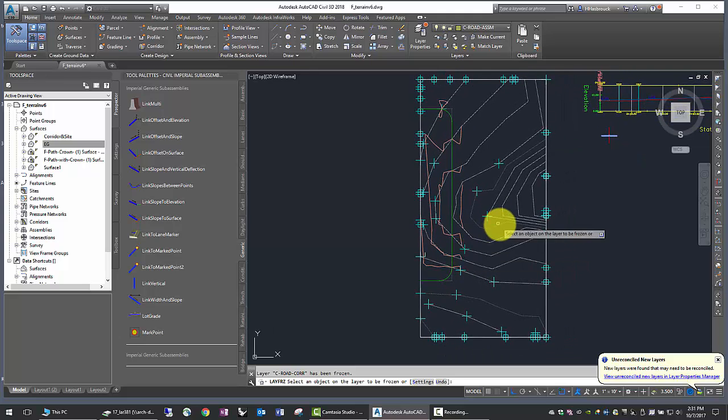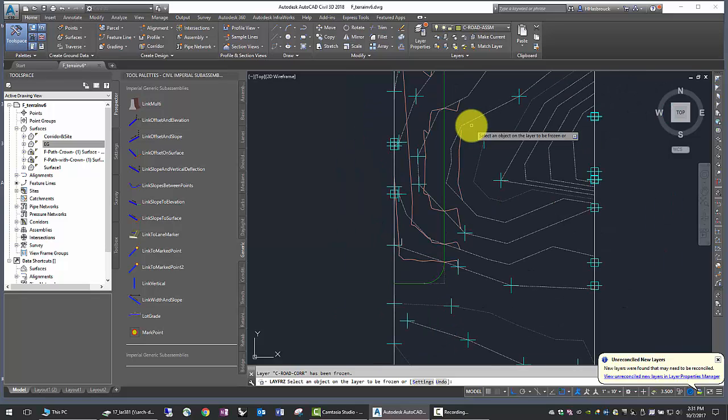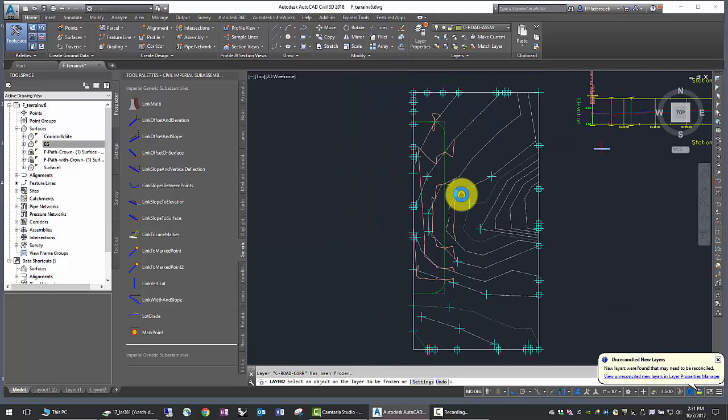Good. Now there are situations here where you can get really fancy. You can add a break line so that the ground turns precisely where you define. So that corridor surface is just like any other design surface that you've seen before. So in this situation, you're beginning to prepare for submitting the assignment.